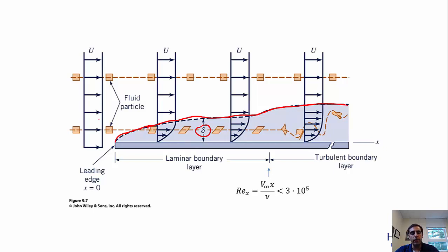When the flow is laminar, you can see the fluid particles entering into this region, and because of friction, developing some shear, which is distorting the shape of that fluid element. Eventually, as the flow progresses further down the plate, the Reynolds number reaches a critical value where the flow becomes turbulent, and that creates turbulent mixing where the fluid elements are tossed and turned and shearing a lot and get highly distorted as depicted in this image. Outside of the boundary layer, the particles are far enough away where they don't really feel the effect of friction caused by the plate.